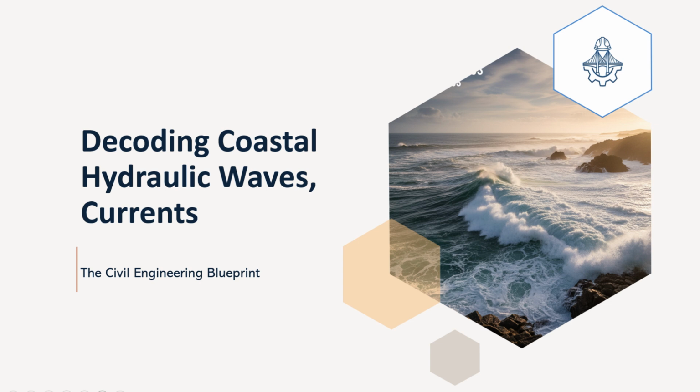Understanding their formation and likely locations is key for coastal safety planning. Absolutely. And finally, we have tidal currents. These are the horizontal water movements caused directly by the rhythmic rise and fall of tides. As the tide comes in, floods, or goes out, ebbs, huge volumes of water move, creating currents. These are particularly important for navigation in harbors and estuaries, for designing mooring systems, and for predicting sediment movement in tidal inlets and channels. They can be very powerful in confined areas.